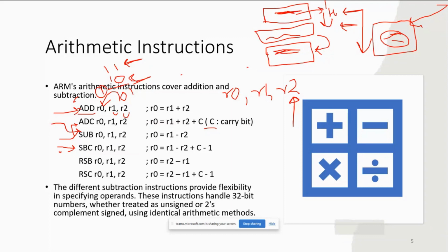एक तो है कि हम R1 R2 को सीधे सीधे सेपरेट कर रहे हैं, वो बात अलग है, बट आर्म हमको कुछ फ्लेक्सिबिलिटी देता है कि हम दूसरे ऑपरेंड में कुछ और कर सकते हैं, सर्टेन मॉडिफिकेशन वी कैन डू एंड देन डू द ऑपरेशन. सो RSB इज रिवर्स सब्ट्रैक्शन. तो अभी हमको R2 में अगर सब्ट्रैक्शन करना है तो ठीक है, बट हमें मैनिपुलेशन जो है R1 में करना हो कि R1 को हम 2 बिट शिफ्ट करके फिर सब्ट्रैक्ट करें. सो बट द अकॉर्डिंग टू आर्किटेक्चर, here manipulation is not possible.